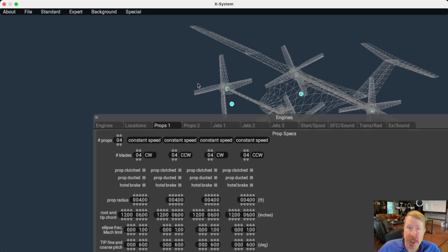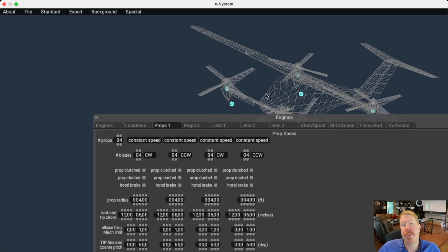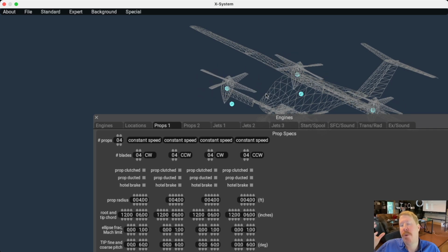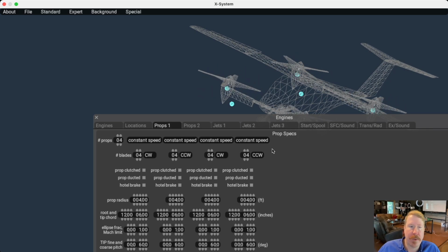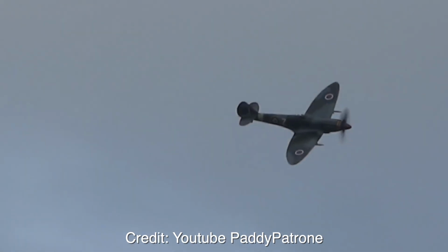And the ellipse shape does get you closer to a minimum of induced drag, because an ellipse planform is a planform that gives a minimum induced drag. And of course, the Supermarine Spitfire fighter from World War II exemplifies that with its wing.